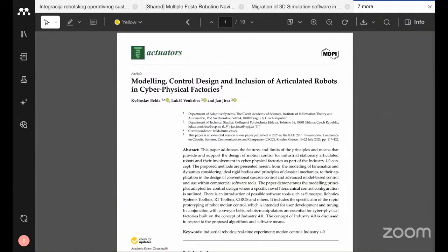So for example, we have a conveyor belt, and in order to pick and place a box from the conveyor belt, the robotic gripper should reach a particular position, right? And also this joint should tilt some angle. So using this, we can calculate this, forward kinematics and inverse kinematics.